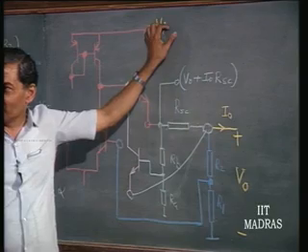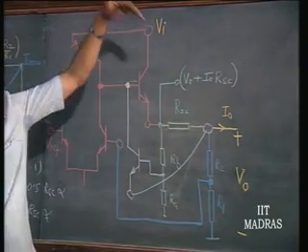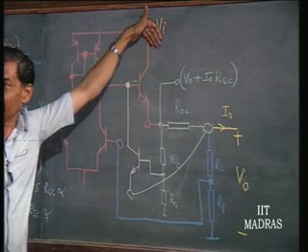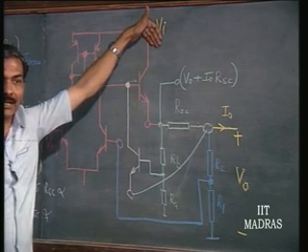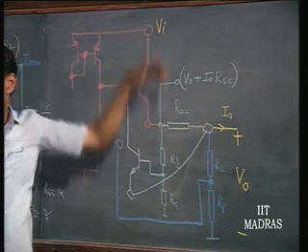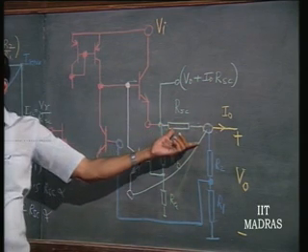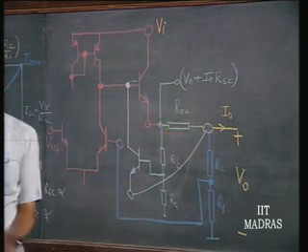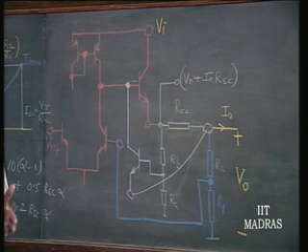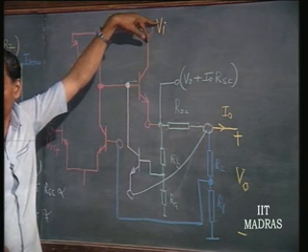Now, the input minimum required is going to be higher than before. So, this is a common error in the laboratory that occurs while testing out this foldback short circuit protection invariably, because in your enthusiasm to make I hold very small, you will come up with RSC which is going to be very large, wherein a large series voltage drop is going to occur and requiring a Vi minimum which is going to be very high.